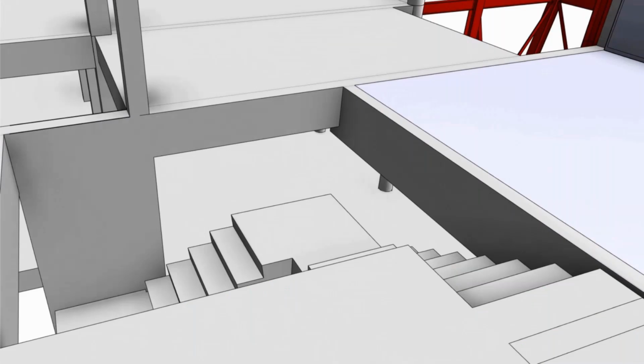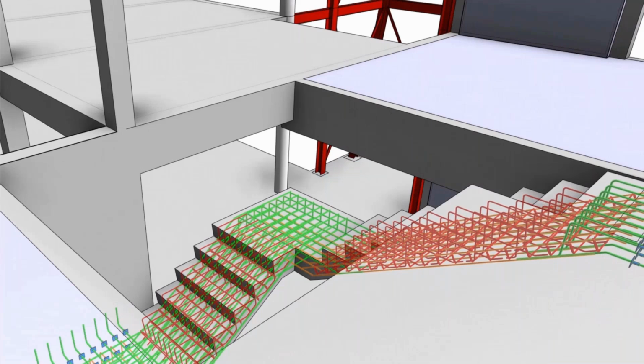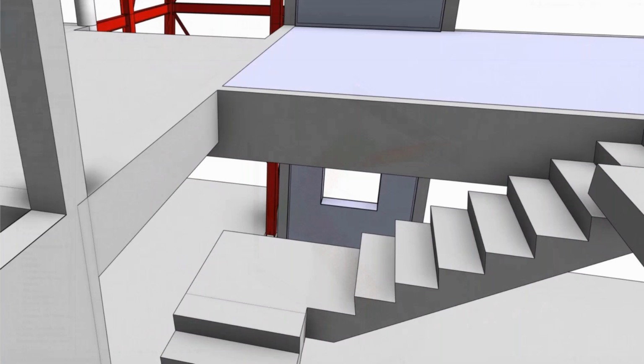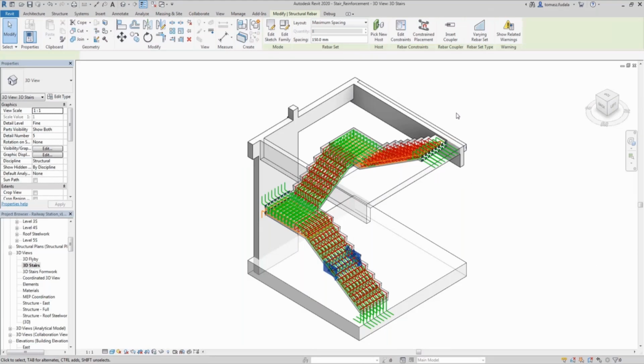You can place the rebars either by cutting sections or using freeform rebars like the one that I showed you, and then it will align and give you all the features that are required for reinforcement and adjust your drawing appropriately. A much easier tool that allows not only structural elements but also model in place elements to take reinforcements. So that's a feature that has been added.